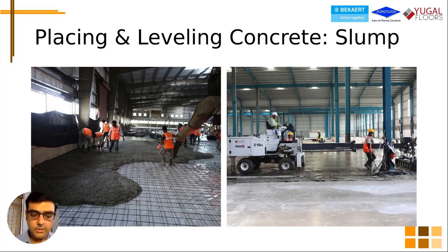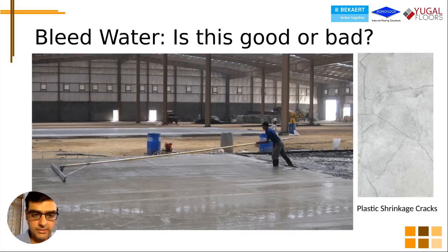Okay, the slide is here. We use a lot of laser screed. The laser screed also needs a certain amount of slump to be able to work properly. I've loaded the second slide while still talking about this one. If you can see, it's a big panel, and it's a fast process. You need to keep pouring, you need to keep leveling. So if you get a tight load, the guys just get stuck here.